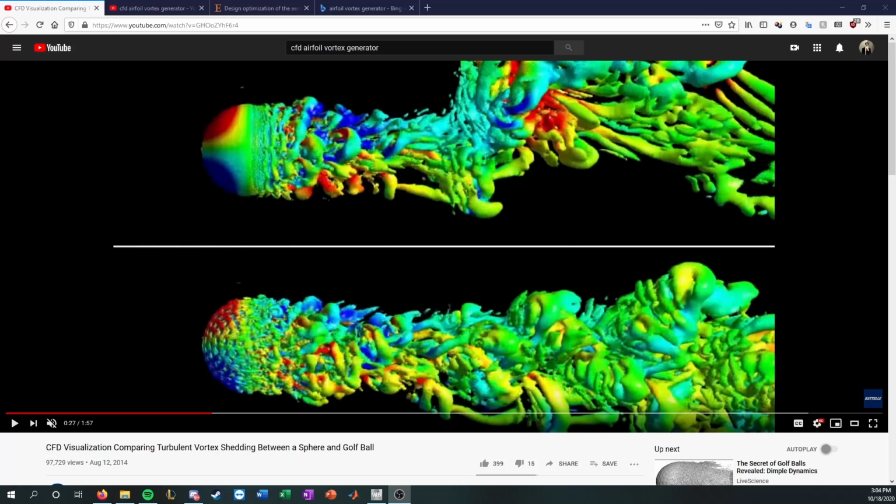And so just to review, hopefully you guys understand that there's a wide range of vortex generators. There are passive and active vortex generators. Active ones are ones where something is actively injecting energy into a boundary layer, like a synthetic jet or something like that. But a lot of the popular ways, maybe for hobbyists or formula students, are passive vortex generators. And a golf ball is the most traditional and I think one of the simplest ways